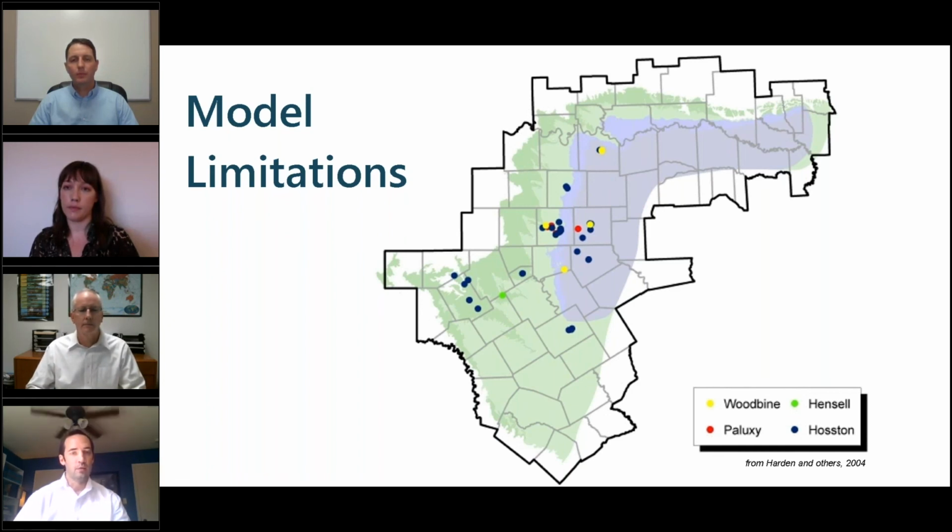To determine if a boundary is appropriate, you can actually test that by evaluating the flow from that boundary and changes due to parameter values or stresses within the model. You can evaluate this and see whether what you're doing there is appropriate. If a stress causes a large change in flow at a boundary, then that means the head's probably changing there, and you probably shouldn't fix it. Artificial boundaries, if applied improperly and not evaluated, can overly constrain the response of the system and create biases in the results.